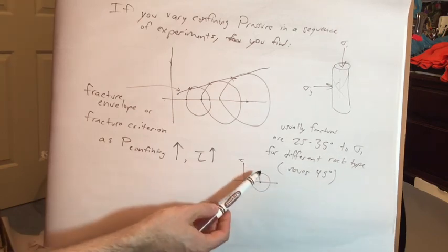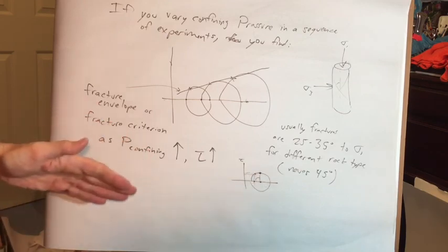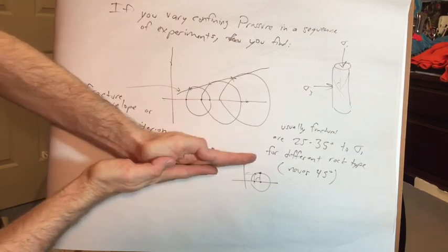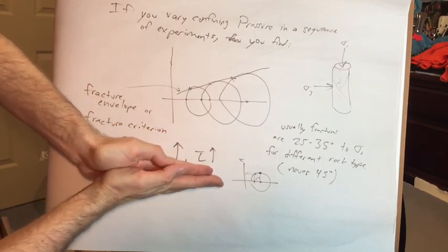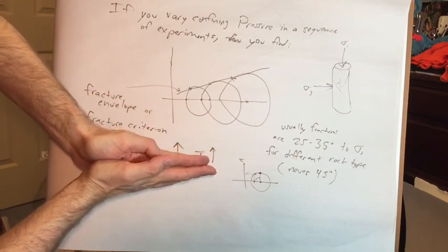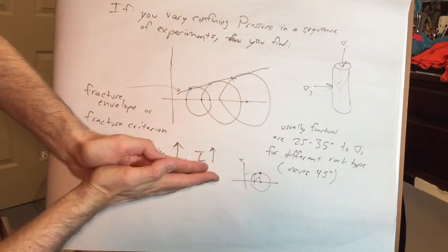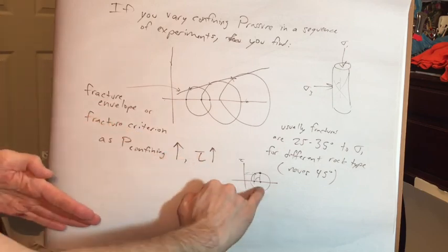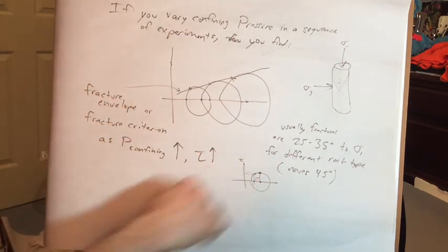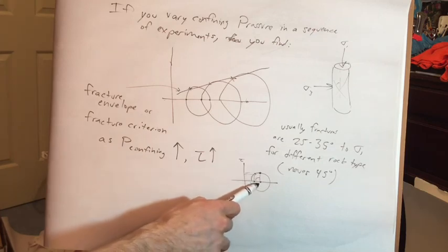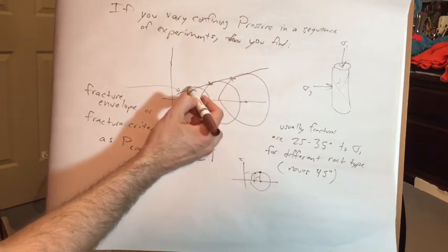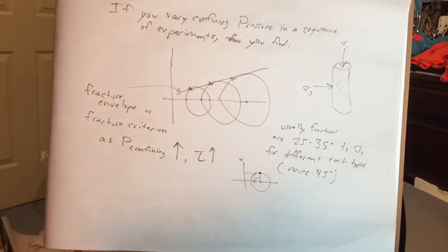So you can imagine, as one of the things that the Moore circle is telling us, if you're going to try to break a fracture on some surface, it's easiest to do it when you're not pushing very hard together, when the normal stress is pretty small. So we can apply almost the same shear stress if we're over here, but significantly decrease the normal stress. So that's why these fractures are occurring not at the maximum shear stress, but still pretty high.